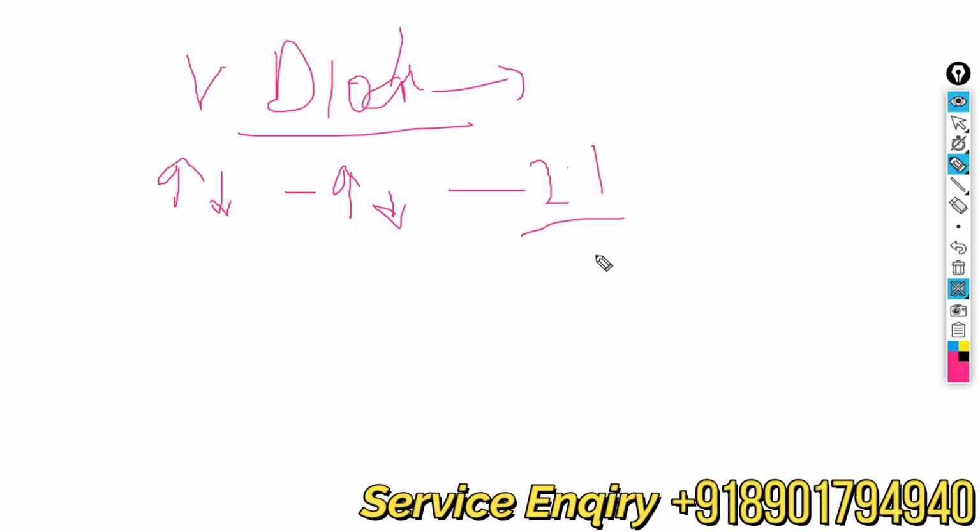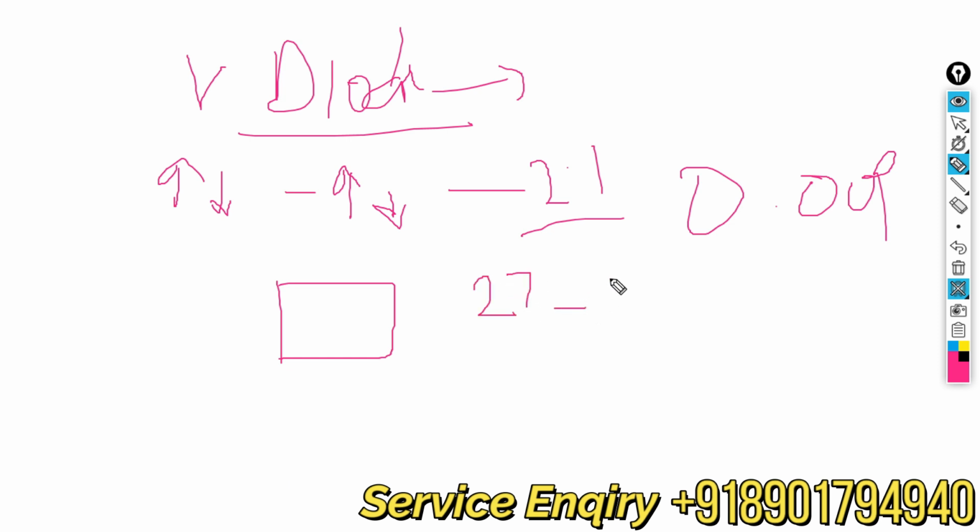right? Clear? Now when we inject, I mean to say check with the DC power supply on the battery connector, and I am pressing the switch, the reading is like, say, before pressing the switch it's 0.09. After pressing the button it goes to 27, 45, 61, 100, 145 milliamp, approximately 100, let's say.